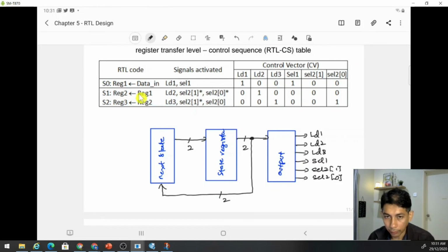Okay, do you have any input? No, this ASM does not depend on any input. It will change the state just after this operation. One clock cycle, the next clock cycle will be this one, the next clock cycle will be this one. All right, so there is no input to this finite state machine. The only input is the clock, and we will use negative edge clock.